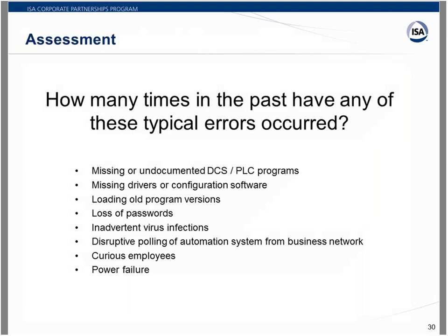So we're trying to get at how frequently these happen. How often have you had this in the past? Look back at your old work orders. Most of the people on this call will say, oh yeah, I remember last year we had a dead PLC and it took us 3 days to get the PLC program loaded in it. Or last year we had some problem on the business network when it was pulling up inventory data. That happens twice a year and I have to call IT. That gives you an idea of how often this is occurring. So it's at least happening that often. If you can design a system to mitigate those problems, you've already mitigated a lot of what would be called your external threats for cybersecurity.